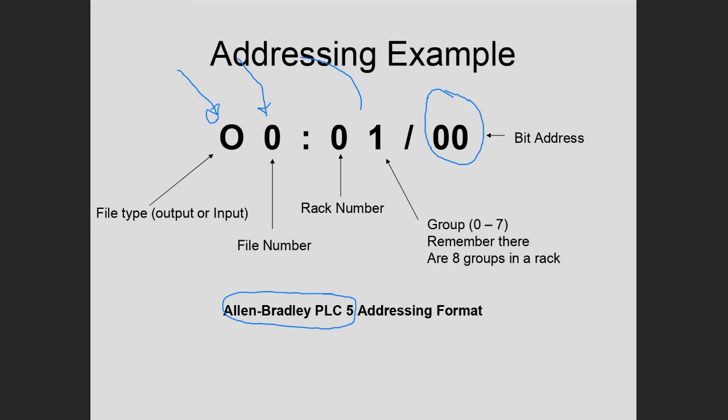So I can go from the Y down to a specific bit location, and either physically, if I'm talking about a physical output module, or if I'm looking in memory, I can figure out specifically which cell that 0 or 1 is stored in. And so addressing becomes important.